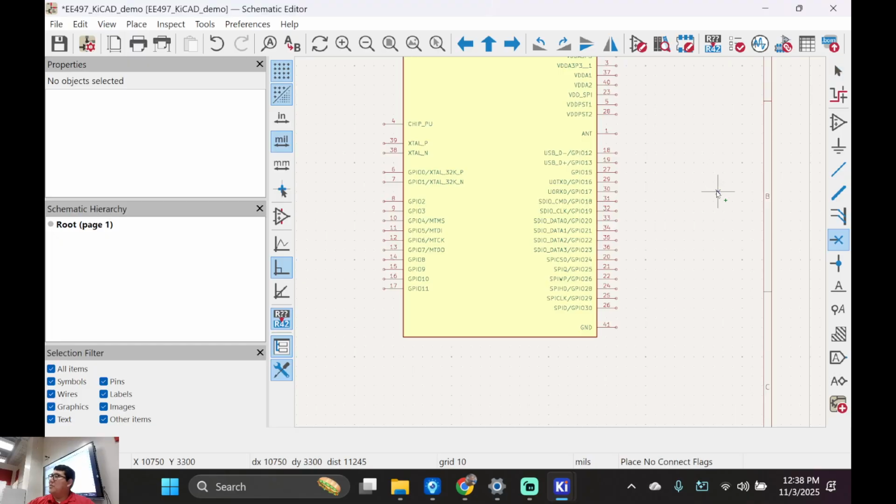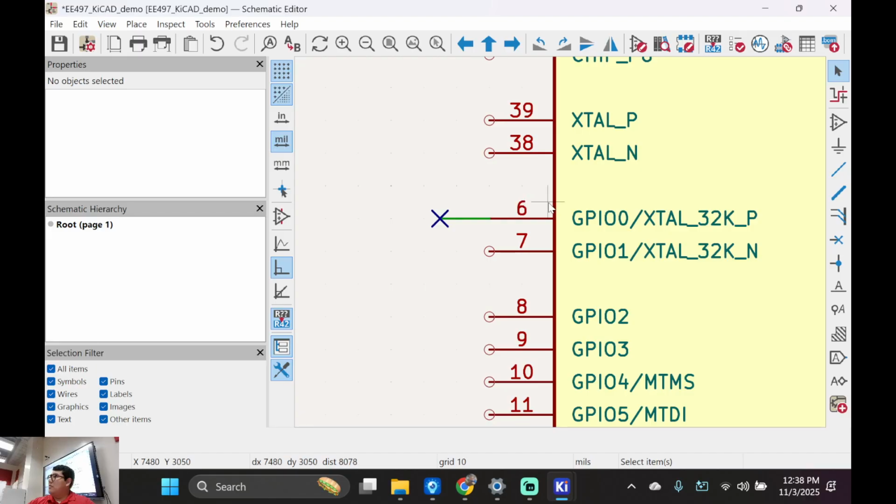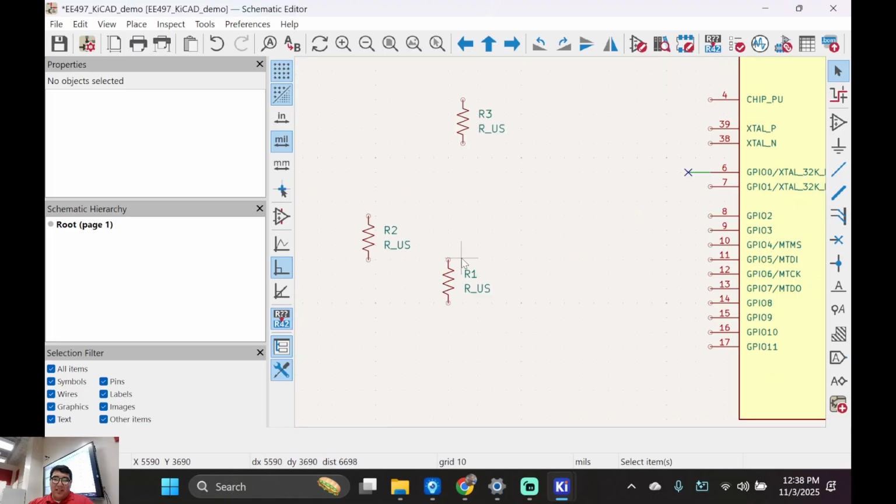no connections. No connections are basically to tell the schematic, when you're doing a check, if I were to connect this wire like this, GPIO, general purpose input output, I'm telling the schematic I mean to have no connection. So you're purposely telling KiCAD, this is no connection. I purposely made that no connection. But you may need, I don't know, I need general input 1 or whatever.